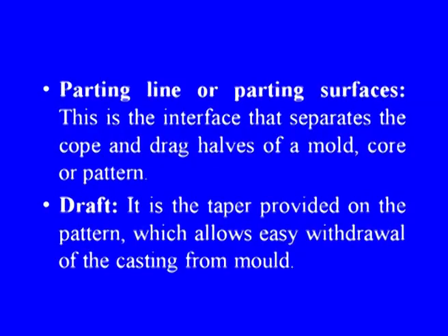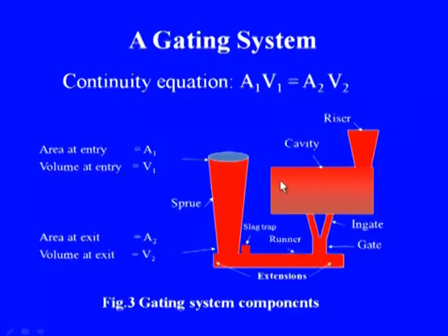Then another very important terminology as far as casting is concerned is the draft. It is the taper provided on the pattern which allows easy withdrawal of the casting from the mold. This we can see in the previous figure as well, as a taper.